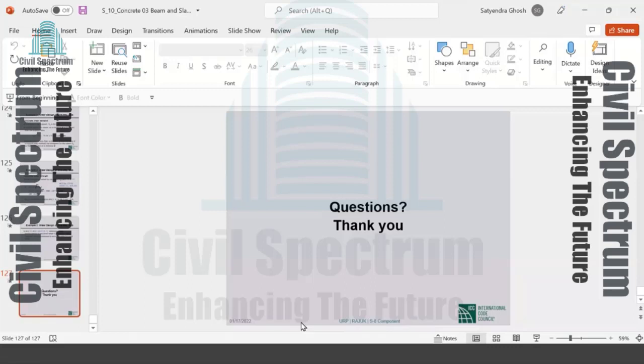Don't quote me, check it out. But even when you don't have a deep beam by the definition in ACI 318, you have a beam that has a depth of, I believe, more than 900 millimeters, you need skin reinforcement. But the horizontal shear reinforcement in a deep beam is mandatory.